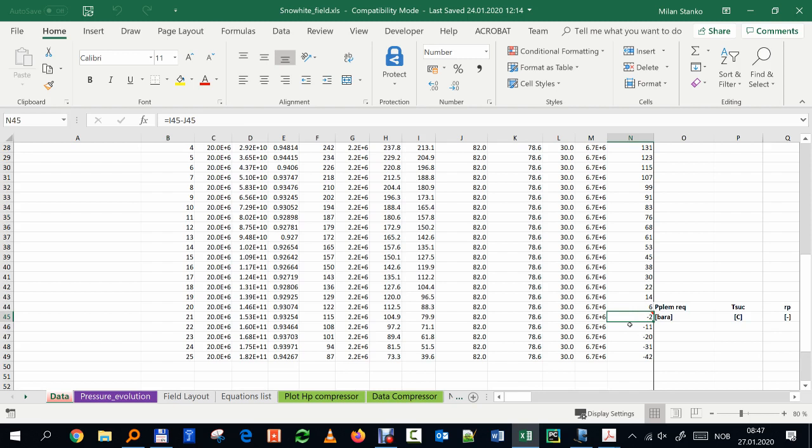Okay, the energy I have is not sufficient to flow against the separator. So, open the choke. When the choke is open, what happens with wellhead pressure and template pressure? The pressures equalize.